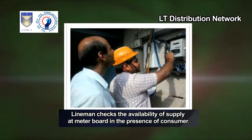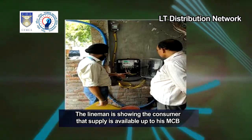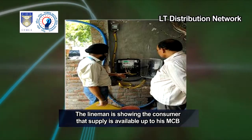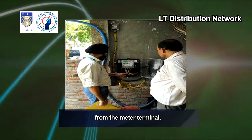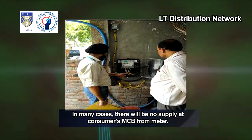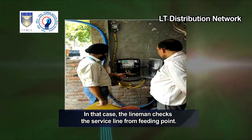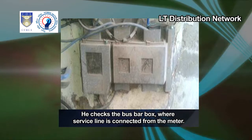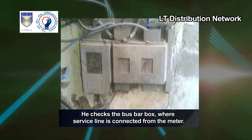Lineman checks the availability of supply at meter board in the presence of consumer. The lineman is showing the consumer that supply is available up to his MCB from the meter terminal. In many cases, there will be no supply at consumer's MCB from meter. In that case, the lineman checks the service line from feeding point. He checks the bus bar box where service line is connected from the meter.